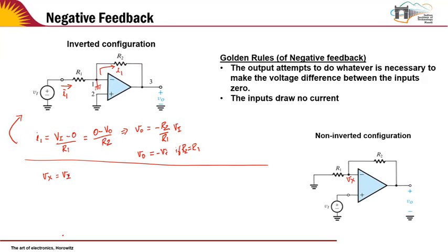And since this is at a value Vx and it's connected to ground, so current has to flow. So there is a current I. What is the current I going to be? I is equal to Vx by R1. And as we know that no current can flow into the op amp, so the same current is given by V0 minus Vx over R2 because of current continuity.